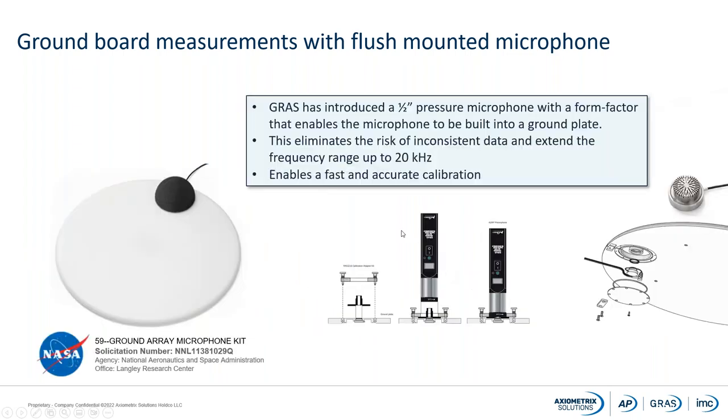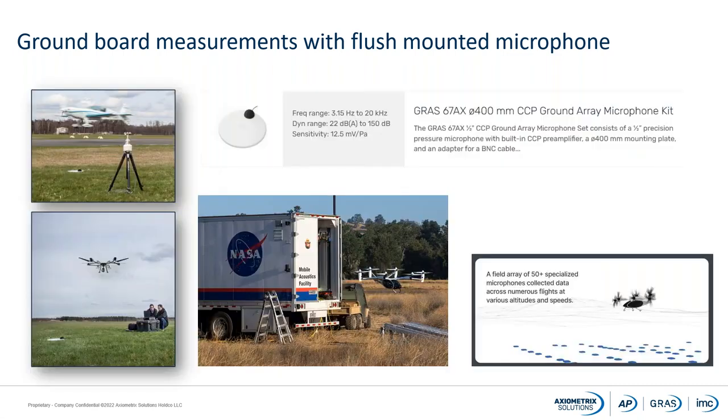What is also a very good advantage is that we actually have an adapter where you can put it on the microphone directly, and you can do a field verification or a calibration directly on the plate. So we can use the pistonphone or we can use a calibrator on top, and we can do the calibration verification of the measurement chain just before we go live and do the measurement. So everything that they already had in the standards, but was difficult to actually make, we have made into this microphone.